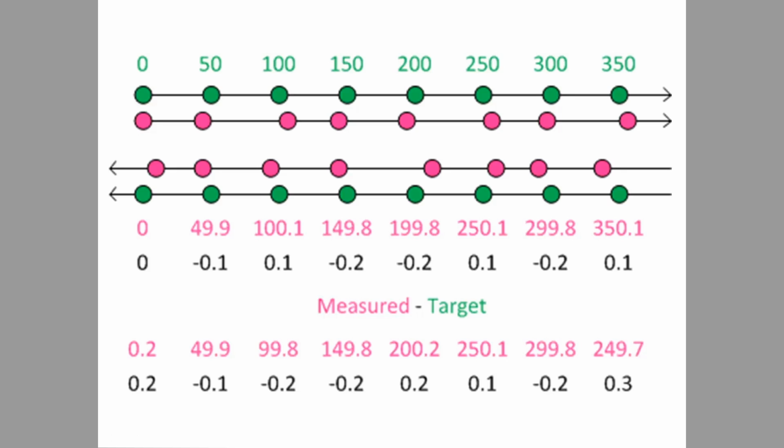The trick starts showing up when you start doing multiple runs. So let's say we're going to do 3 bidirectional runs, 6 runs total. The problem is that we start getting that little bit of noise from repeatability at x equals 0. So what that ends up meaning is that when we start looking at our comp values, the x0 in the positive direction, where we zero the laser, starts getting small numbers. There's 2 choices we can make. First choice is we can just ignore it and have both tables technically being correct. There's nothing wrong with them. But there'll be a small value of comp at x0 in the positive direction. For many machines, that's just fine.